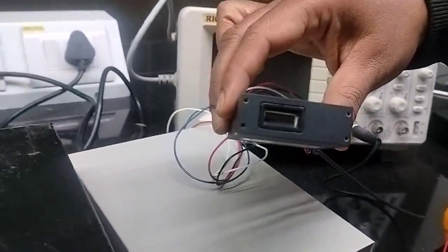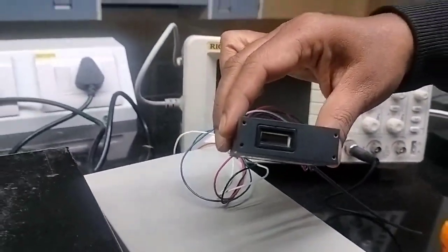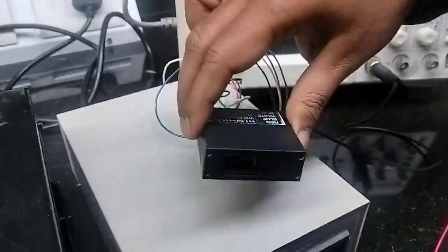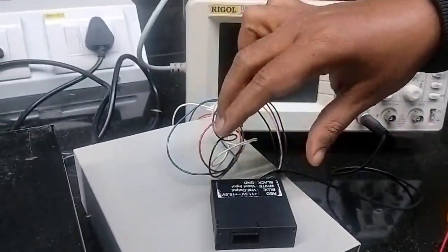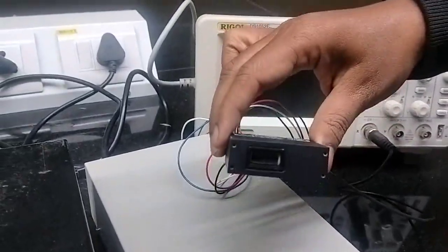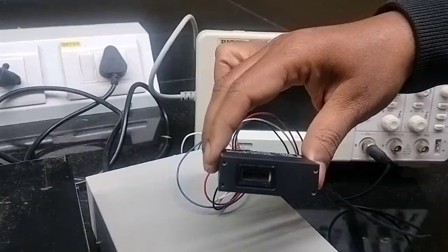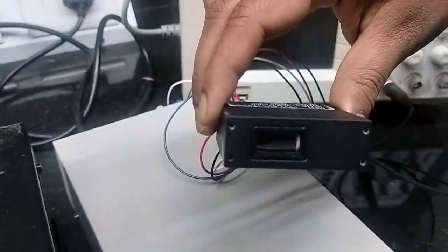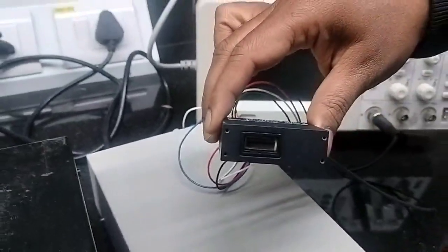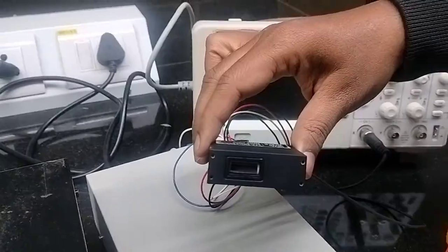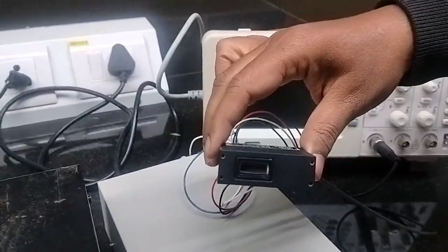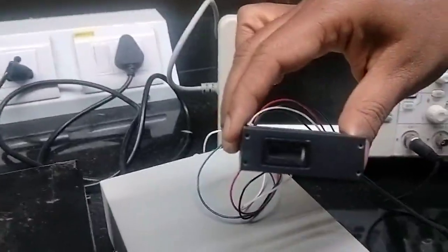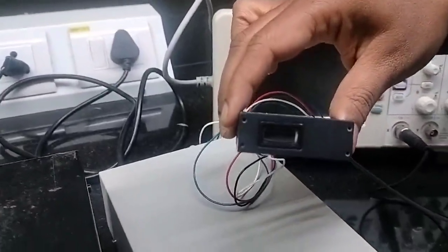This module contains a built-in high voltage power supply circuit and a 13 mm diameter side-on photomultiplier tube, in a compact aluminum housing. The PMT uses a reflection mode multi-alkali photocathode, provides a gain of the order of 10^6 and has a UV glass window.